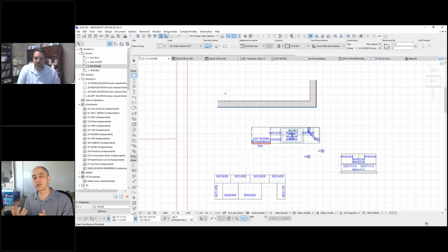If you migrate to the new library, anything that Graphisoft considers an identical part, in other words they didn't change it, will carry over perfectly. Anything that Graphisoft considers a revised part, it will leave your reference in the old part. It will not change it.